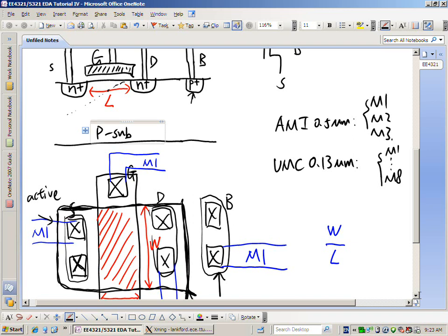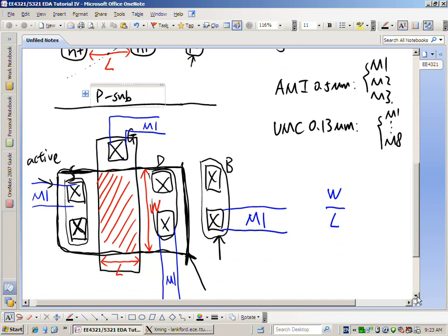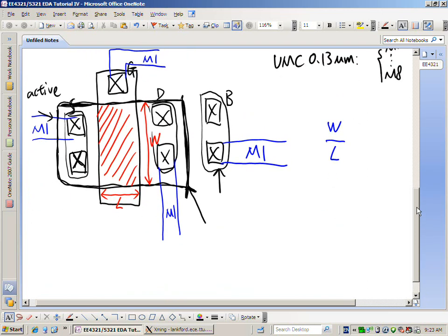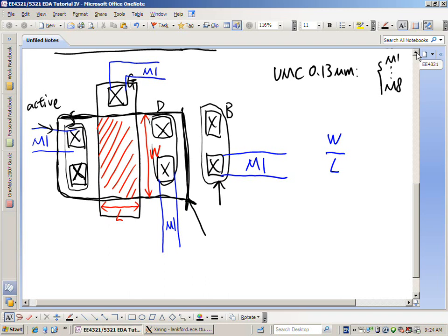Okay. So the companies are trying to make the most efficient procedure for you to do the design. Okay? But would they let you just make two active regions? I don't think so, because if you make two active regions, a lot of times the software cannot recognize this as a transistor. You have to do extraction, and the rule for extraction is it has to identify one active region, and on the active region, you should have the polysilicon gate.